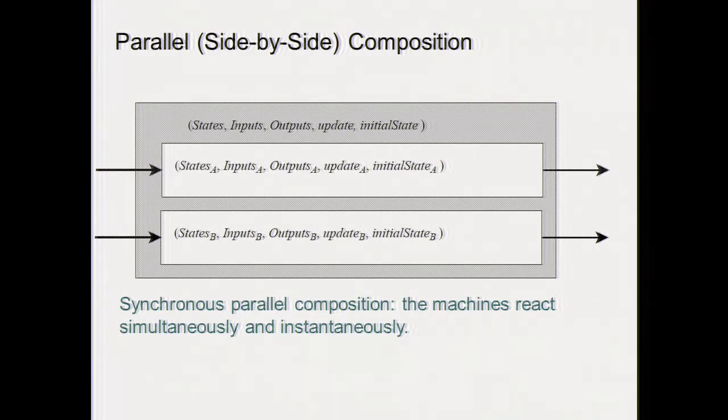And so what is it? How do we combine the models in a parallel composition? Assume that I am a finite state machine, and here to the right is another finite state machine. Now the parallel composition, remember everything happens in lockstep, says inputs come in, I take a step, my friend here takes a step.